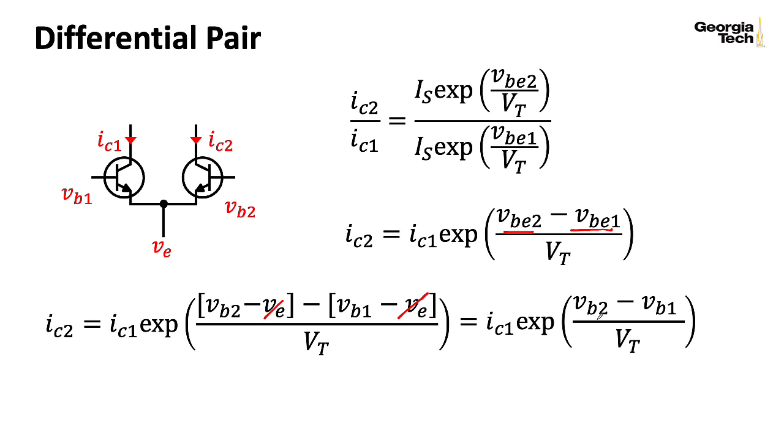Now, this is not a particularly novel calculation. This is the sort of calculation you do if you want to study operational transconductance amplifiers made with BJTs. This is also just the basic of a differential amplifier pair that pretty much shows up in any analog circuits class. It's the front end of every op-amp that has BJT inputs. And if you're using MOSFETs or JFETs, well, it's the same kind of structure, just with MOSFETs or JFETs. So lots of kinds of circuits have this kind of structure at their input.